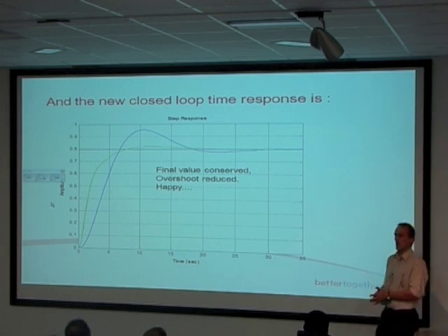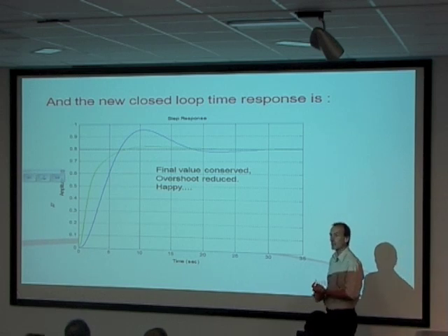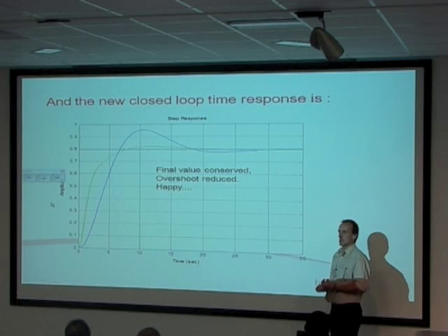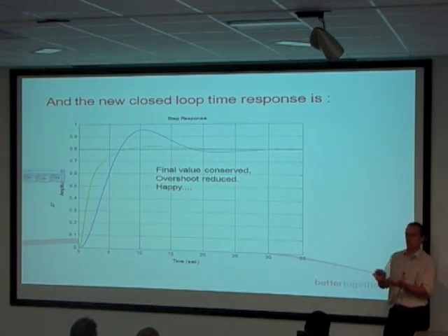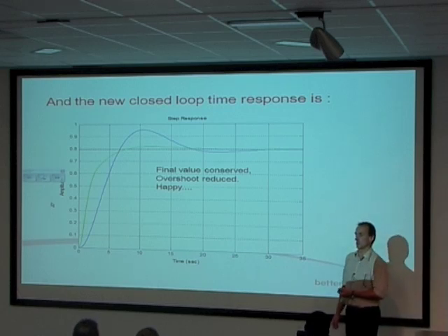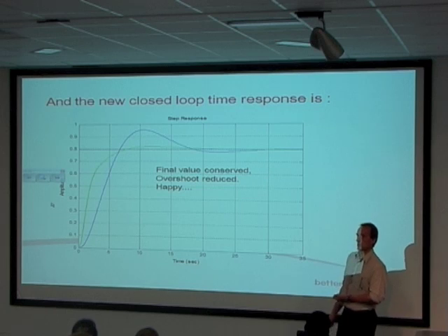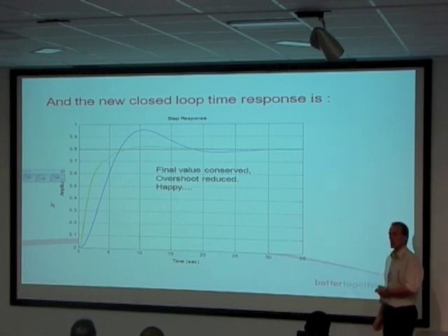So we've managed to introduce a compensator using a standard pattern. I picked a lead compensator for this exercise. If you wanted to design one, you go into the compensator design books and there are off-the-shelf formulae for how to do it. That gives you the numbers to put into your lead compensator. So it's a very straightforward design process.